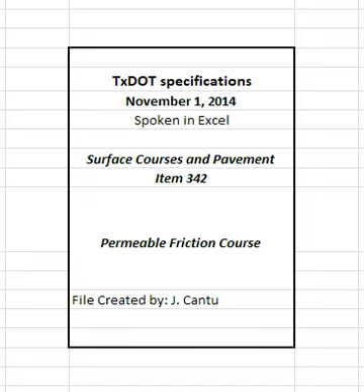4.9.1 Referee Testing. The construction division is the referee laboratory. The contractor may request referee testing if the differences between contractor and engineer test results exceed the operational tolerances shown in Table 5 and the differences cannot be resolved. The contractor may also request referee testing if the engineer's test results require suspension of production and the contractor's test results are within specification limits. Make the request within 5 working days after receiving test results and cores from the engineer.